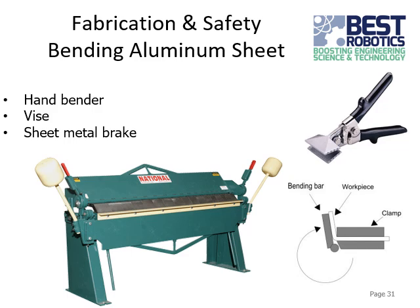Do note that if you do too tight of a bend, like if the radius of the bend is too sharp, you can actually break the aluminum. It'll just snap. So it can be helpful to put something like a dowel rod or something rounded on the inside of the bend that you bend around, so that you have a nice gradual curve, and that can keep the metal from breaking.